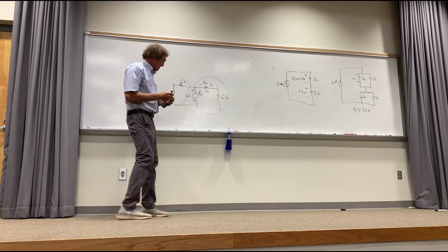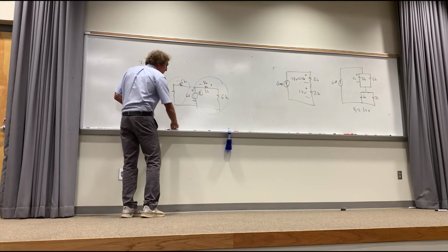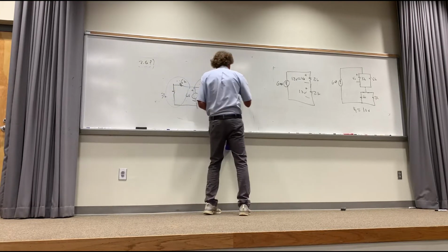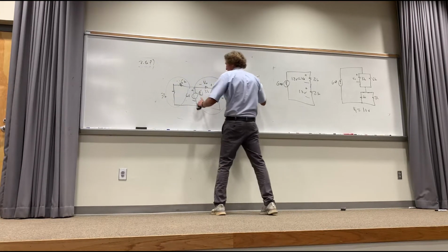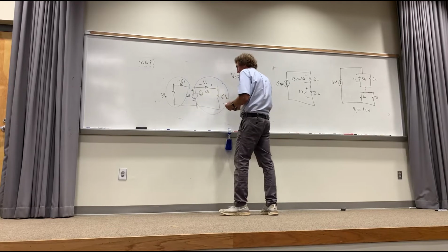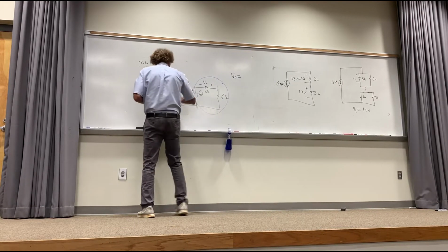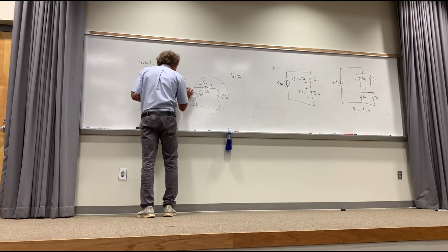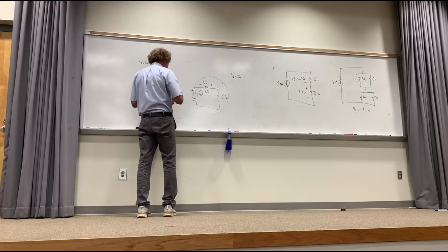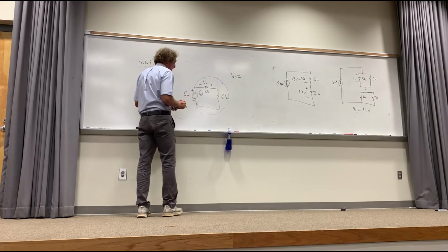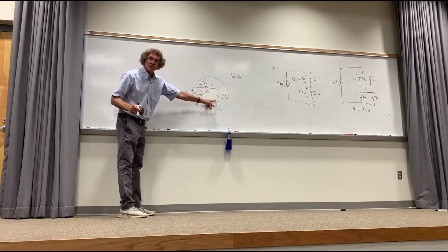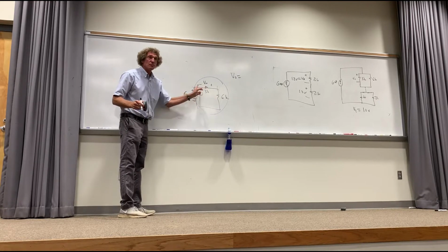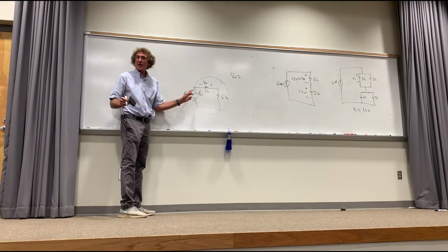And if they're in series, that means that voltage V out, now we use voltage division, V out is going to be equal to the net voltage. As a matter of fact, just to make the point, you don't need that part of the circuit. You can get rid of that. This is 6 volts. And it's dropped between these 2, isn't it? These are the only 2 resistors that are in series, correct?